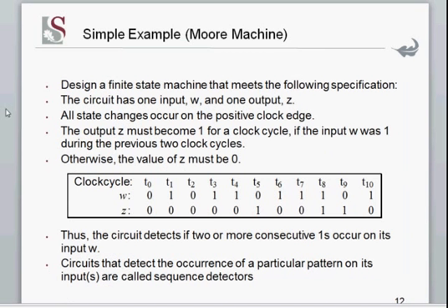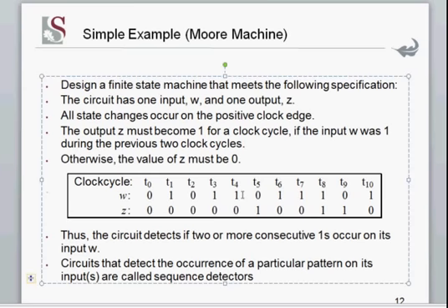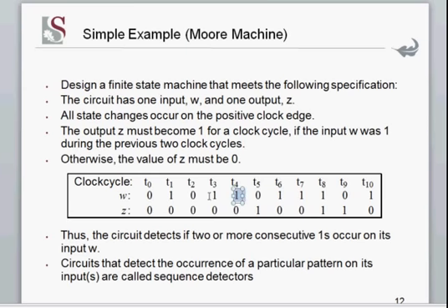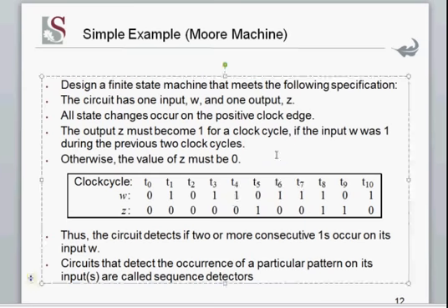Okay, so the easiest way to look at these state machine concepts is really through an example. The example that we're going to do is we're going to develop circuitry to perform a sequence detection. And the sequence that we're going to have to detect is a sequence of 2 ones. So in this slide here, you can see an example of what the circuit's supposed to do. If it detects for 2 clock edges, just be careful. The textbook uses the word clock cycles. That should really be clock edges. It implies more or less the same, but it's a bit of a subtle difference.